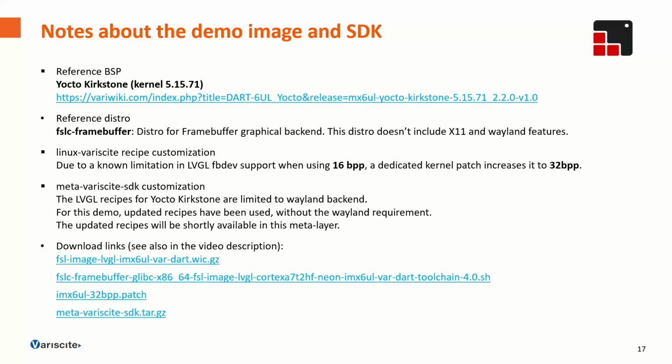About the Variscite SDK, our layer is the layer where we have, let's say, the user space customization. We introduced specific LVGL recipes, because if you look at the mainline of the Yocto layers, you will surely find LVGL applications, but they all mandatorily require Wayland.